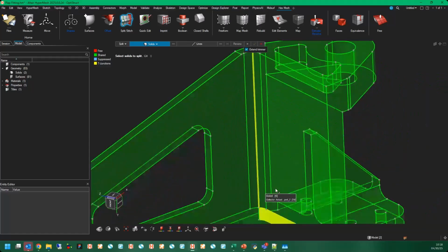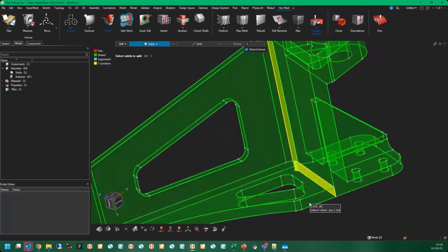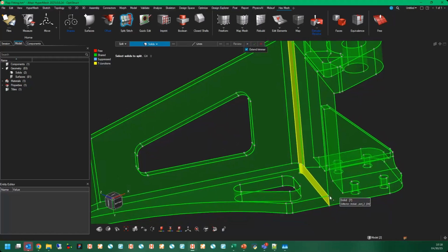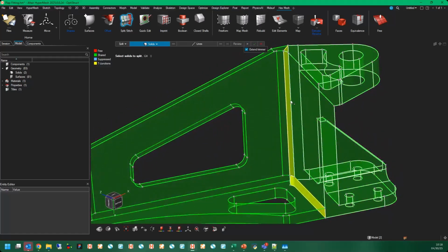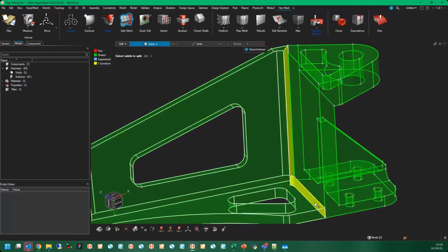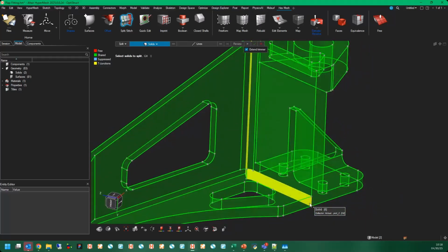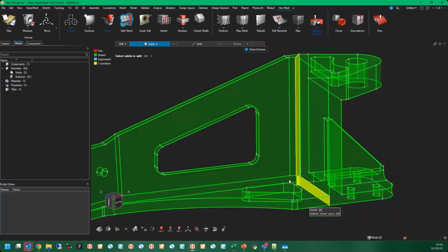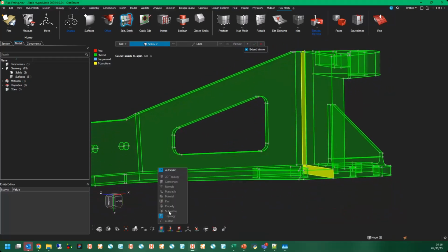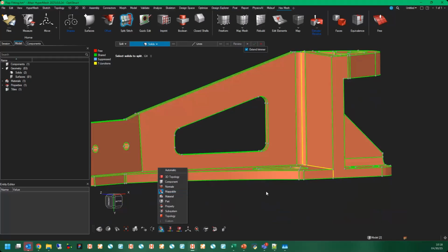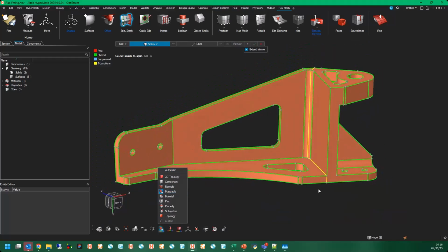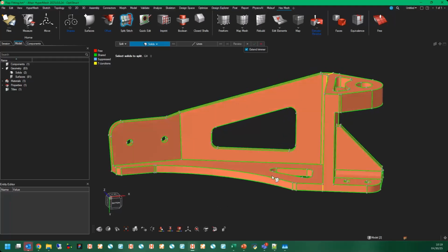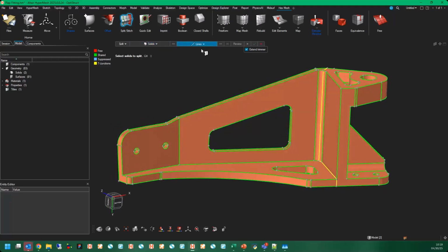All right. So now I'm in 3D topology mode here, which is also useful. I'm going to switch over to Mappable in a second, though. In 3D topology mode, the yellow faces indicate shared faces. So those are the ones that we just split, the boundary between the two solids that we have in our model now. But like I said, I'm going to switch over to Mappable so I can get a better read on my progress. Right now, everything's red, which means that nothing is mappable because it's still too complicated. But let's see if we can break down the left half of this to start off with.